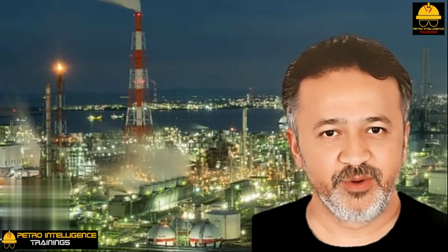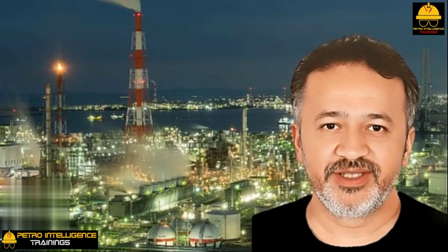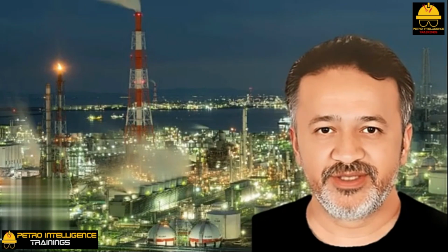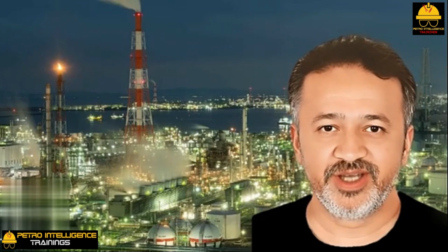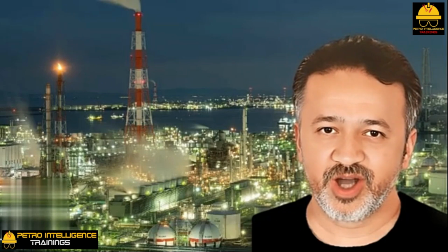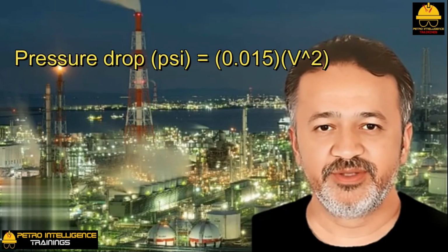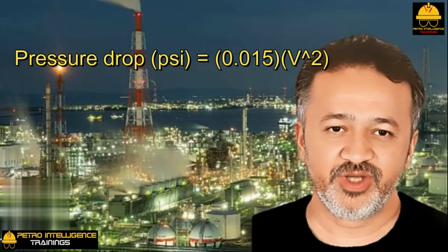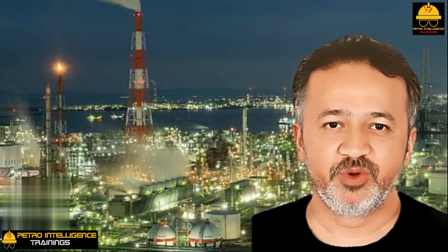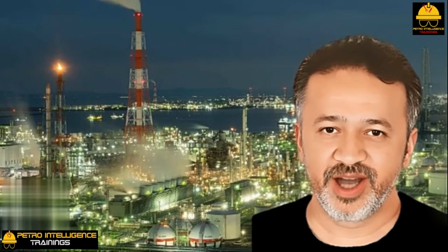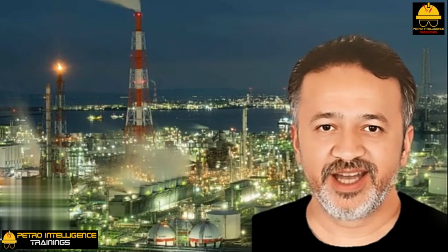Condensate drainage and vapor lock. As steam condensate flows through process piping, it loses pressure due to frictional losses. Alternately, condensate draining from a reboiler outlet nozzle will accelerate and lose pressure according to this formula: pressure drop, psi, equals 0.015 V squared, where V equals feet per second. For example, condensate draining through a nozzle at 10 feet per second would undergo a delta P of 1.5 psi.